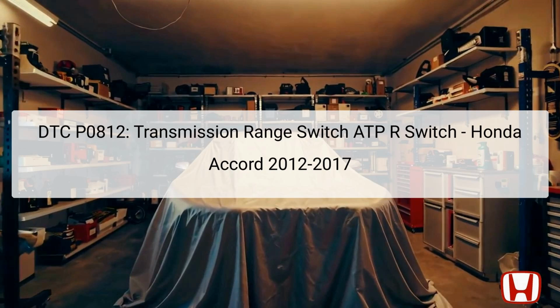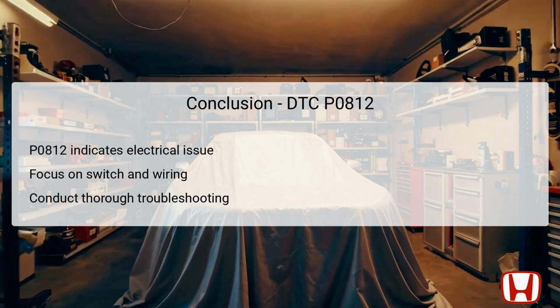It's important to note that this code does not relate to mechanical issues within the transmission itself. Therefore, any troubleshooting steps should focus solely on the electronic side, including checking connections, wiring, and the switch itself. Before beginning repairs, ensure to gather all relevant freeze data and on-board snapshots using the HDS, Honda Diagnostic System, for accurate diagnostic insights. In conclusion, the DTC P0812 highlights a concern primarily rooted in electrical issues concerning the transmission range switch rather than mechanical transmission problems.